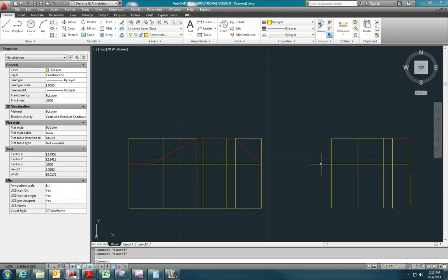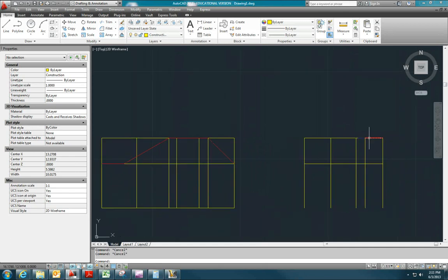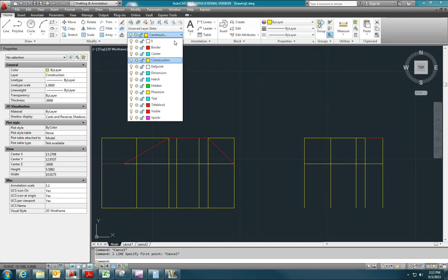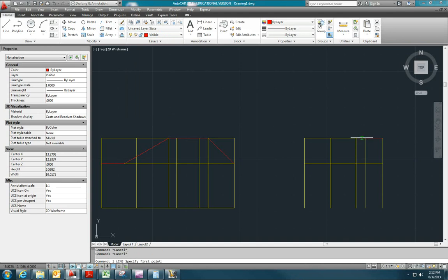So now let's see. From the top surface of the object in the right side view, the object slopes forward by 45 degrees. Okay, so let's draw that line now. I think that'll help. Let me go back to my visible layer. So I want to go to 45. 15, 30, 45 is right there. Trim off the excess, TR, enter, enter, and then click. And then I will draw a line straight down and then back to the beginning here and then up to the top.